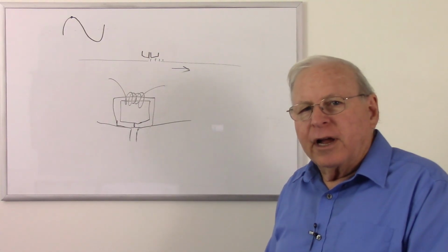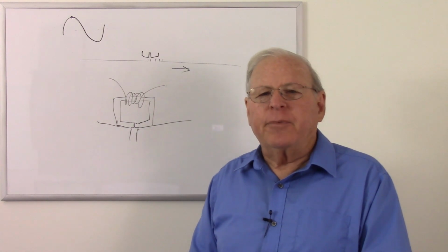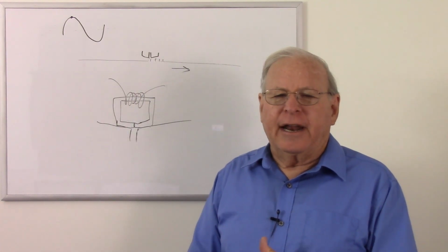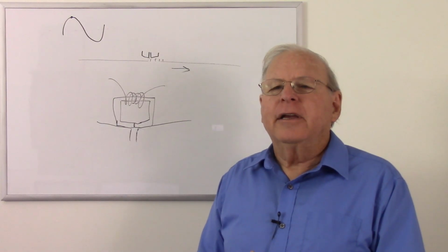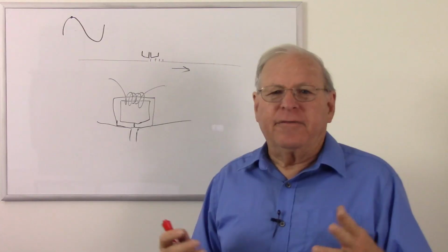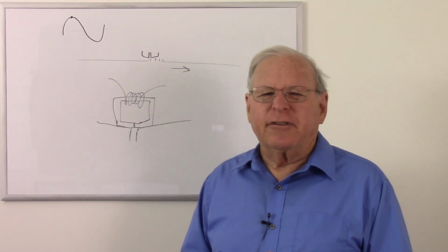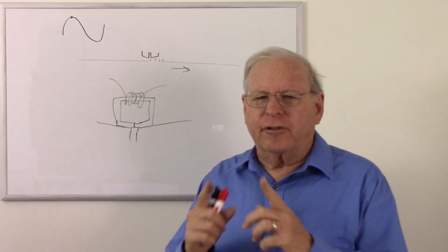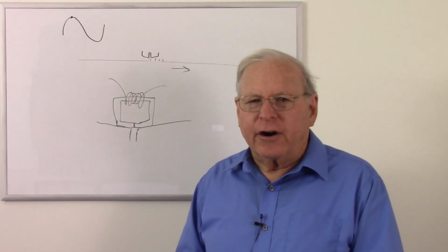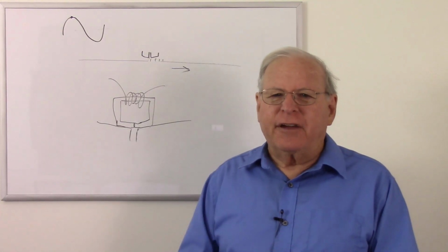But what if you are not so interested in high frequency response and you want your tape to last longer? A 1200 foot tape would last about half an hour at 7.5 inches per second. Well, if you cut that in half to 3 3/4 inches per second, then that tape would last a whole hour. Quality wouldn't be as good, with a maximum frequency response of maybe 10, 11, 12, perhaps 15 kilohertz, depending on the gap, but not as good as the 20 kilohertz or higher of the higher speed. Trade-off: longer recording, less high frequency response.